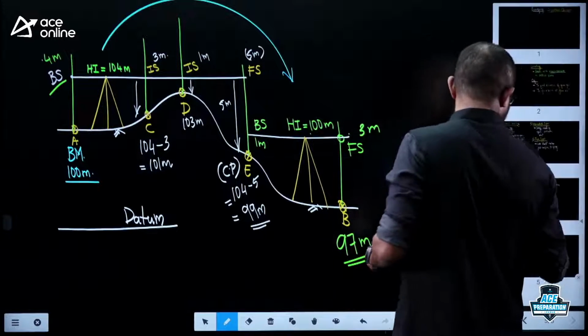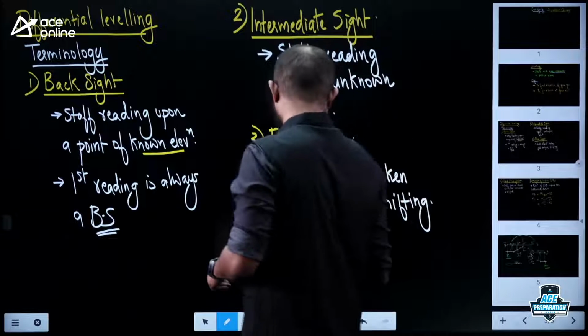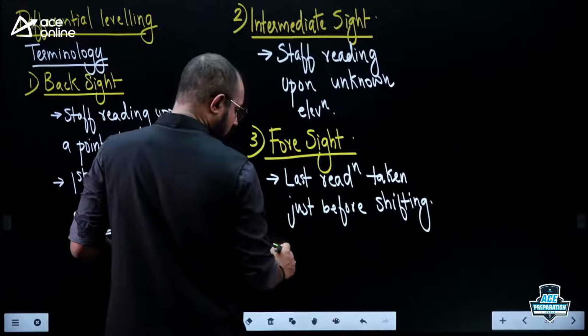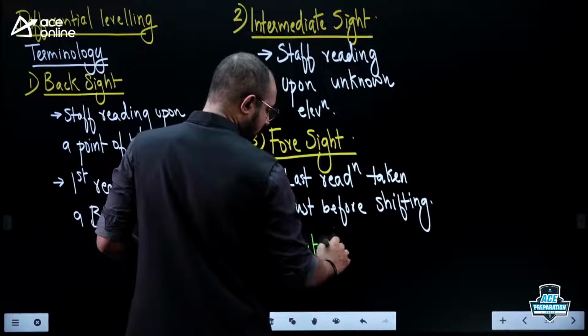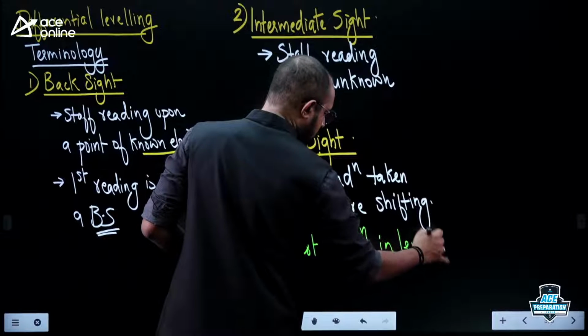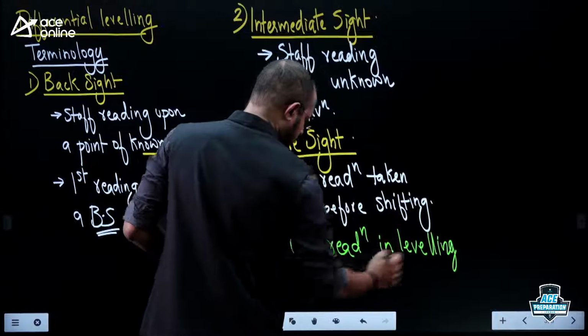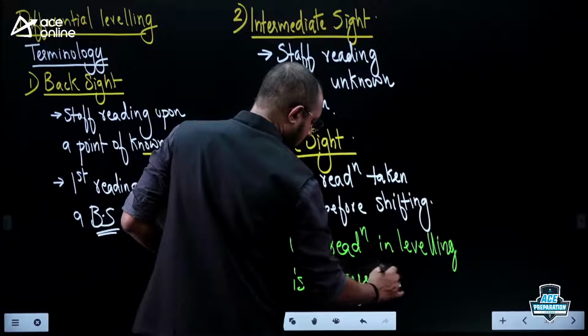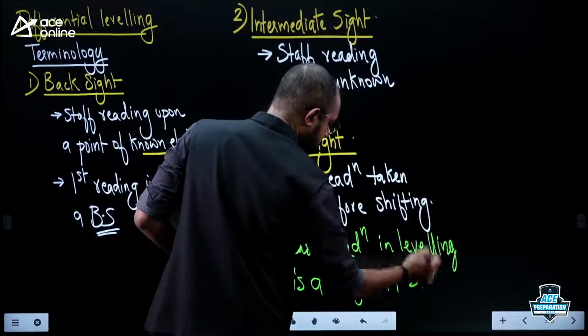So while we are writing the definition of foresight, I can add one more point here. The last reading taken just before shifting is a foresight, and also the last reading in a leveling work is always a foresight. It is always a foresight.